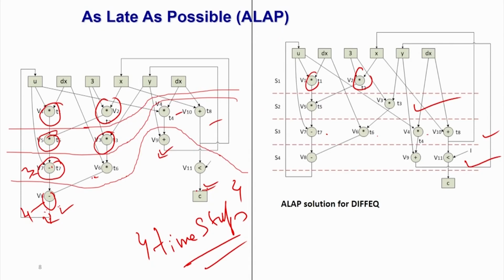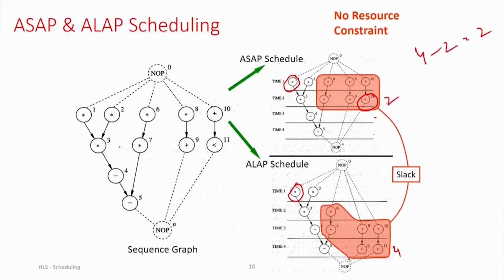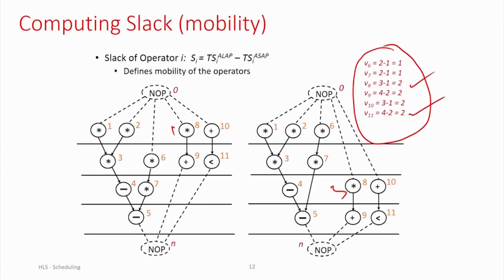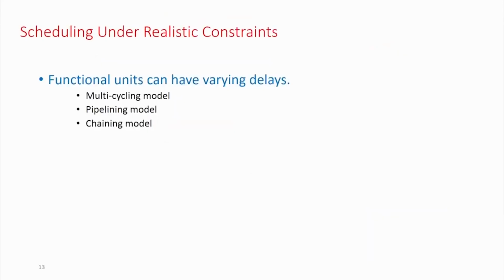Okay, now if we move on, as I discussed, the algorithm in your circuit may have different kinds of complexities. First of all, you might have a resource constraint, right. If you have a resource constraint, that means you cannot use as much resource as possible, you have to schedule everything within a resource bound, right. So, if you have that, then ASAP ALAP won't work. Also, as I mentioned earlier, operations can be of different types, it can be multi-cycle, it can be operation chaining, it can be pipelined.